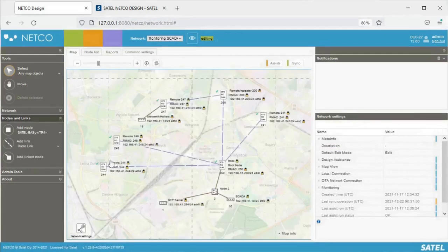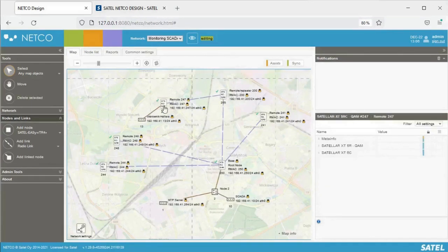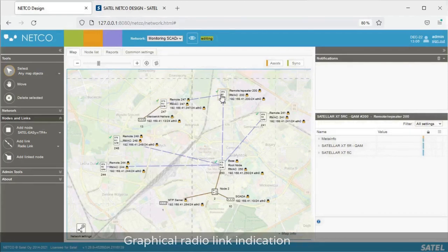As an example, this particular radio network consists of a base station directly connected to 4 radio stations. A remote radio station is used at the same time as a repeater to a remote station where a direct radio link cannot be created from the base station radio. Radio links are displayed with a dotted line and Ethernet links with solid lines.